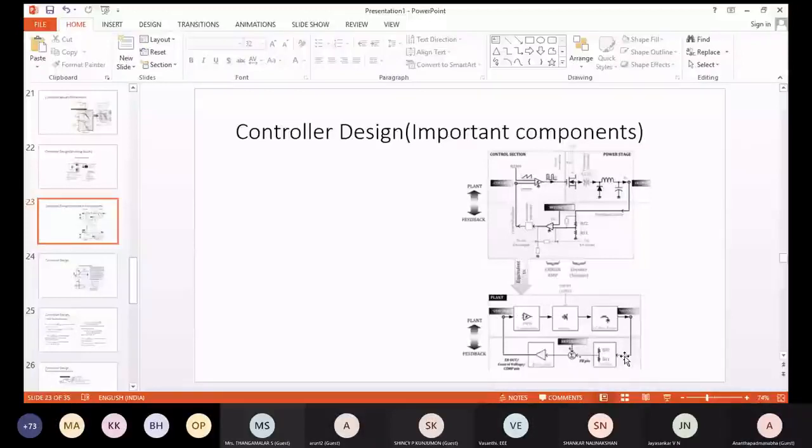So basically there is a voltage divider network, an LC filter network, the power converter, and then a composite error amplifier. These things have to be properly represented as transfer functions, so that we can teach the controller a proper lesson in handling the dynamics. That is the essence.